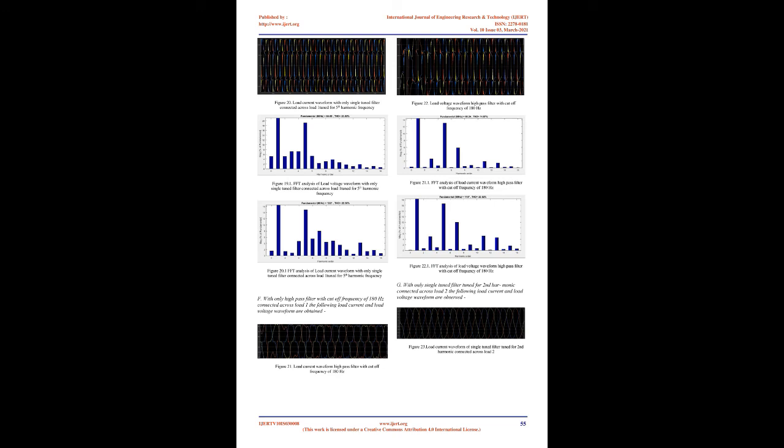The solar PV array has been connected to a grid with 2 unbalanced and 1 balanced load, the details of which are given below. The first load is an unbalanced load connected with a series active power filter for harmonic mitigation. It consists of a universal bridge with snubber resistance of 100 ohms and snubber capacitance of 0.212 mF. The second load consists of a three-phase bridge configuration diode rectifier with on-state resistance of 0.1 ohms.